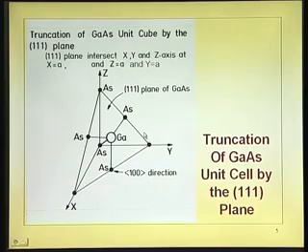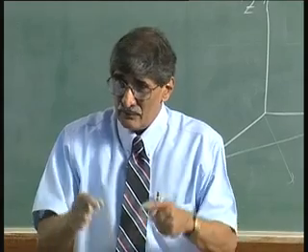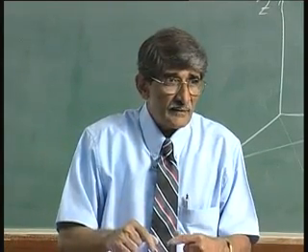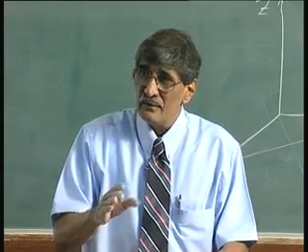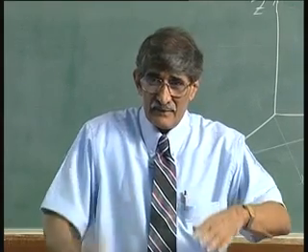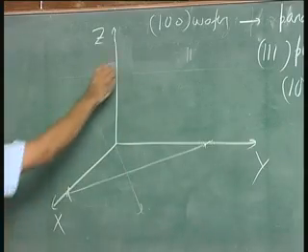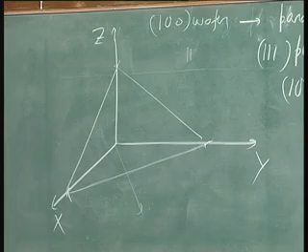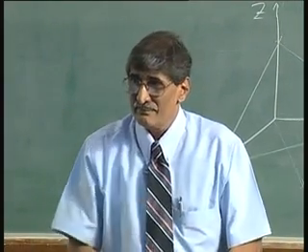So, if you see the wafers, when you dice them into individual chips, you scribe them, make small chips which are 1 millimeter by 1 millimeter, you see the edge of those in silicon, that will be at an angle. It can be like this or like that, because after all there is a plane like this or also going down. So, depending upon which way the force has come, you will see it is going like this or like that.